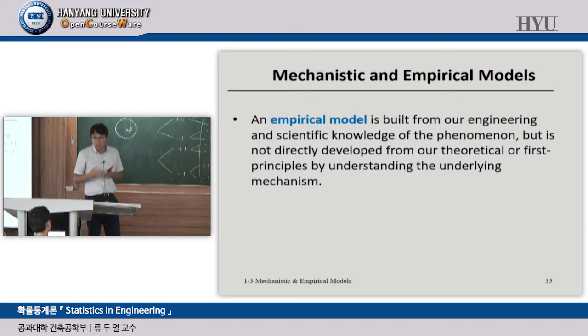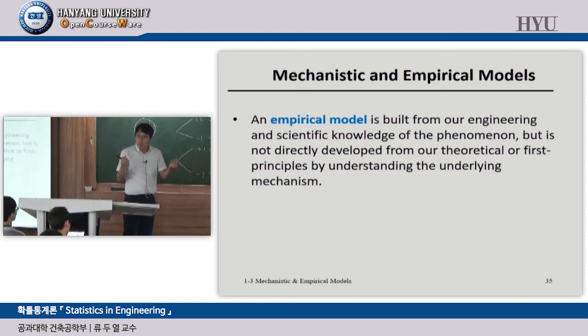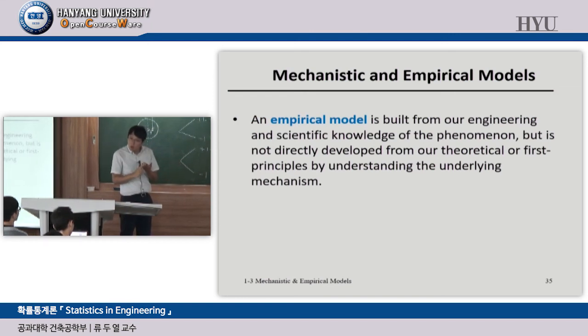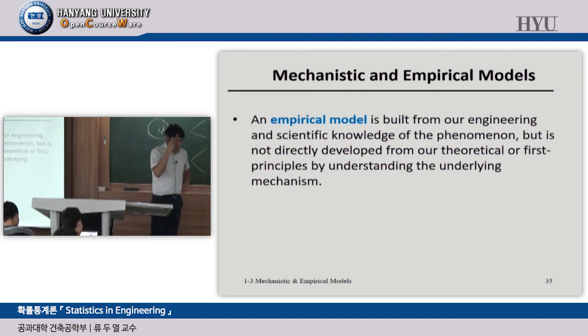It is almost impossible. So what engineers do is that they normally gather numerous data points obtained from different researchers, and they make a relationship between the strength and other factors, such as the ratio of water and cement, the amount of coarse aggregate, the amount of sand, etc. Based on the data points, they can presume the equation using regression analysis, 회귀 분석 in Korean. 그러니까 회귀 분석을 통해서 보통 도출해요. So this is a typical example of the empirical model. And in the architectural engineering field, we normally use the empirical model rather than the mechanistic model because there are so many uncertainties affecting the result of some performance of the construction materials or the structures.